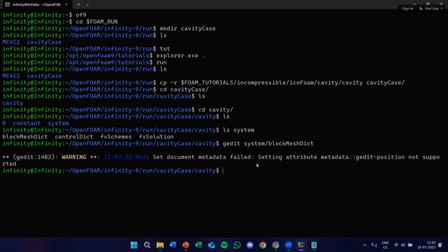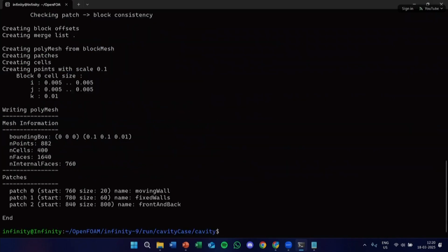Once you're done setting up everything, the first thing in doing your entire simulation is to create your mesh. That you will do using the blockMesh command. So everyone just type this in. Type blockMesh and then press enter. Has everyone done this? Yes. Okay, great.